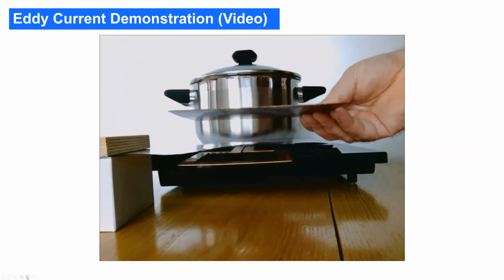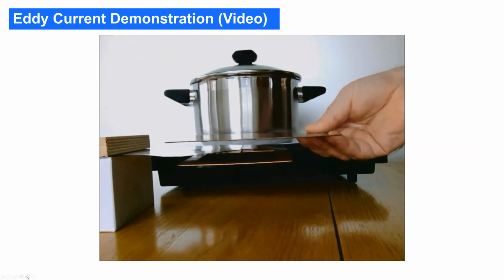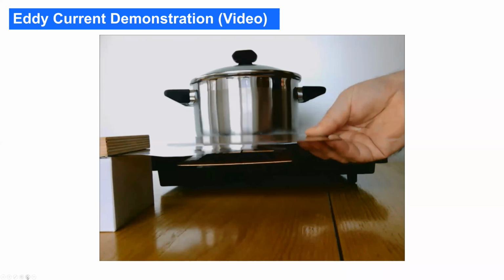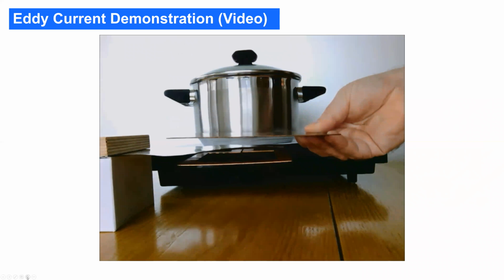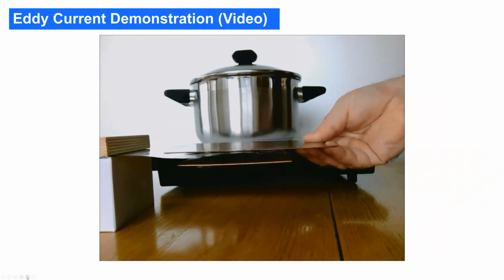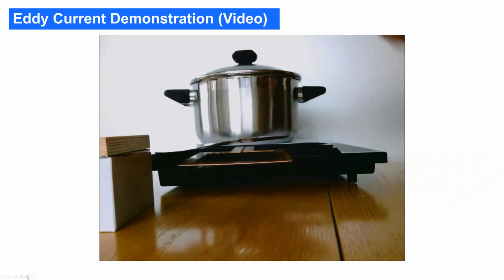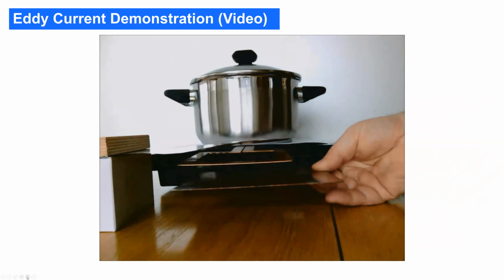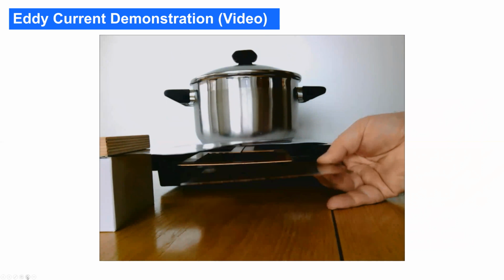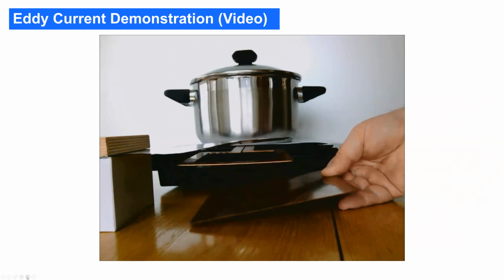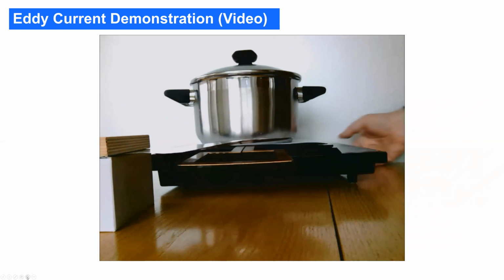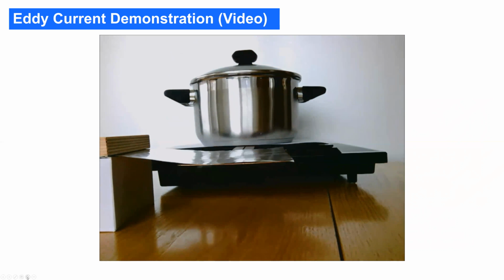Now if I have a conductor, same from the top side. It really doesn't matter if I come from the bottom or the top side. I will reduce the eddy current in the aluminum foil if I have a plain conductor below or above it. And that we can also use if you make PCB boards. So try to make under your hot loop a solid plane as good as possible.